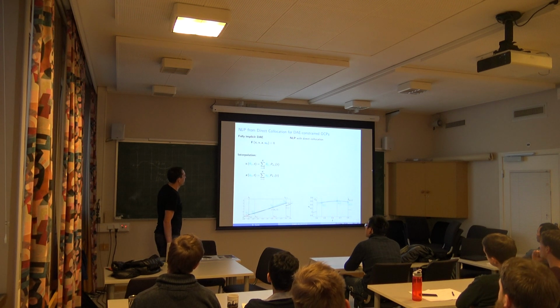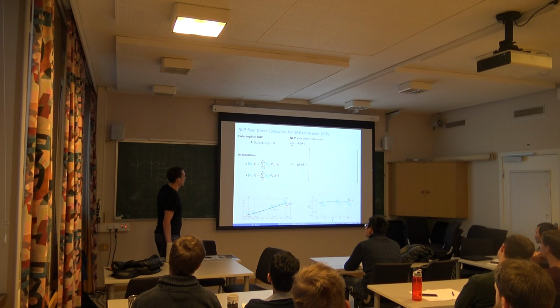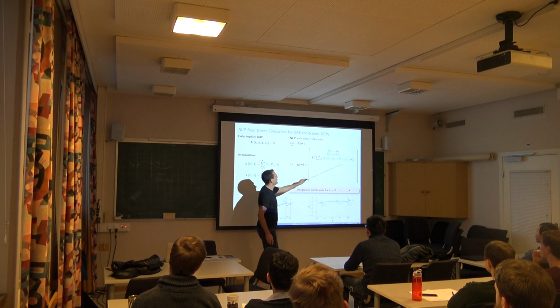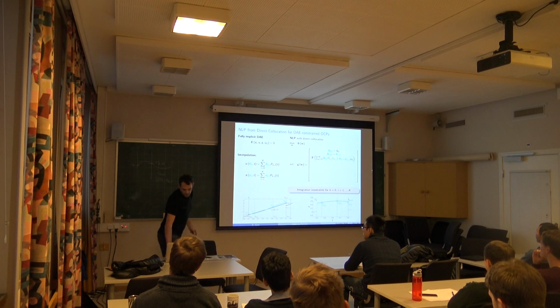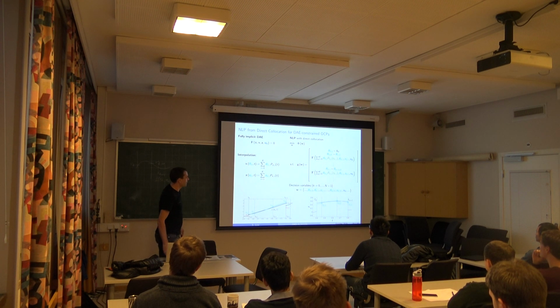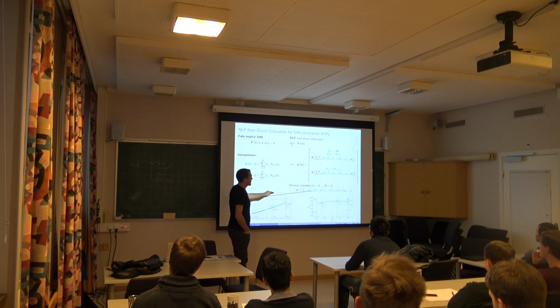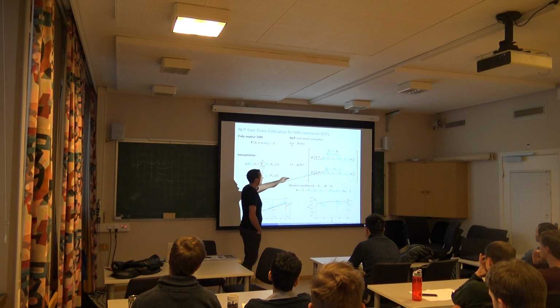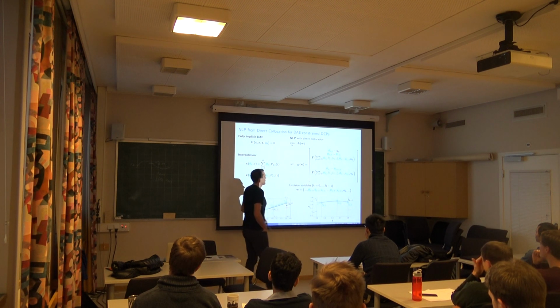So if you have to form an NLP for direct collocation with DAEs, you have the initial conditions, shooting gaps, and then you have your dynamics with the z's appearing now in here, and you have these for every shooting interval. And then in your variables, you have the thetas for supporting the differential trajectories and the z's for supporting the algebraic trajectories.